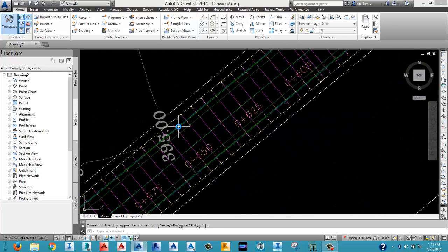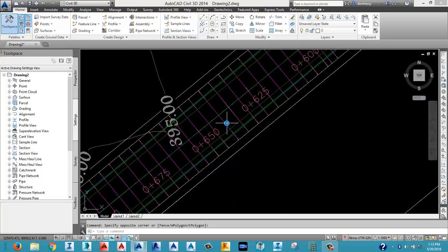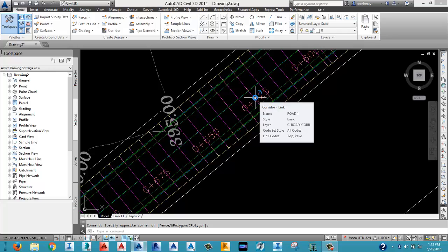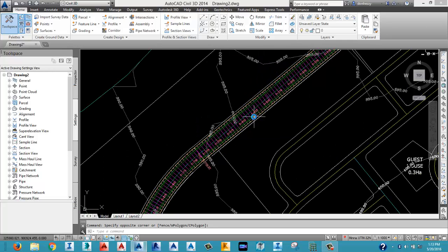There are so many things you have to clean up, because you can't expect the contractor that will be taking up this drawing to have so many lines. So there are many things you do to clean up so you can have a clean output. That's just basic AutoCAD presentation. So after you finish modeling your corridor, you're good to go with your design by doing the final step, which is the outputting.